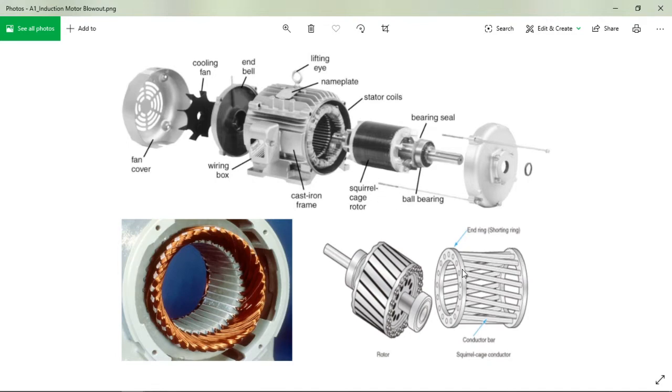Now the rotor has these loops here. There's a shorting bar here and these rods here that conduct, and currents are induced in these rods and it generates a field. And also there's resistance here like there is in all conductors. So basically this field induces a field in here which induces current. This current in turn generates a field which interacts with this field and it tends to rotate.